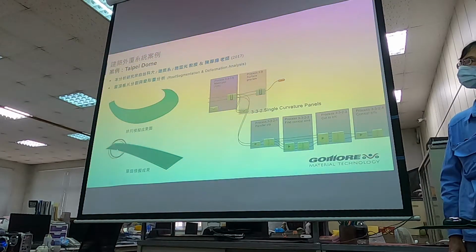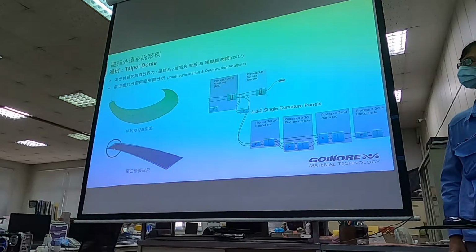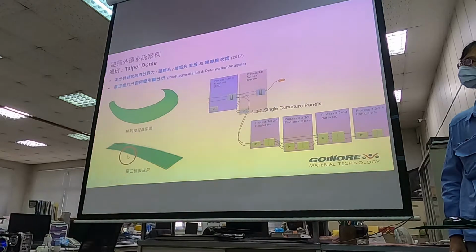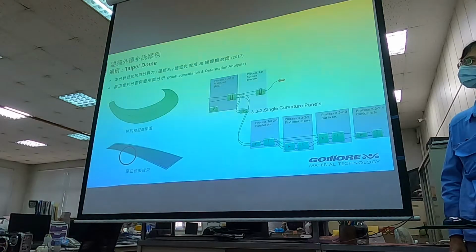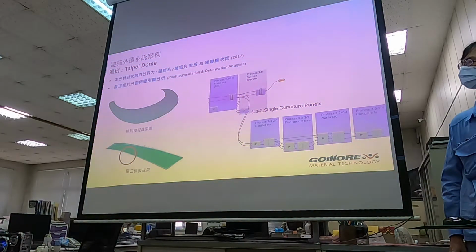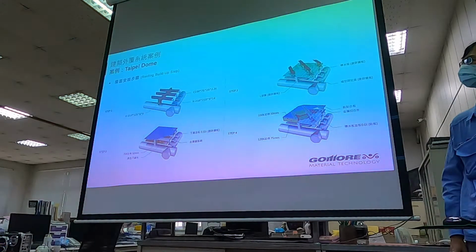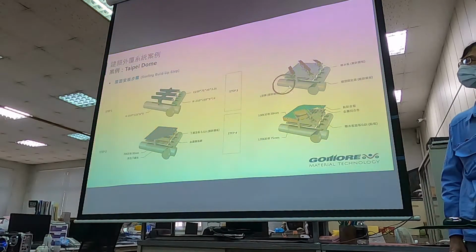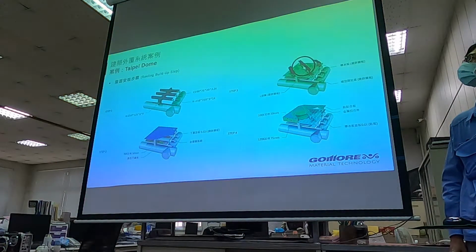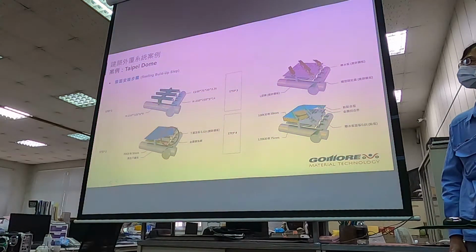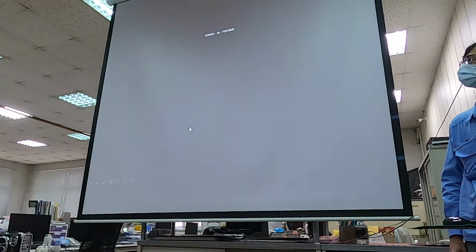In some panels, they might be within the 3D situation. So the length of this side and this edge might not be equal when the panel is actually installed outside. You need to twist the panel, and you find there is a certain edge which is longer than the other edge. So we install the framing, bottom layer and the intermediate framing, and top panel, and into a finished skin like that. Questions?